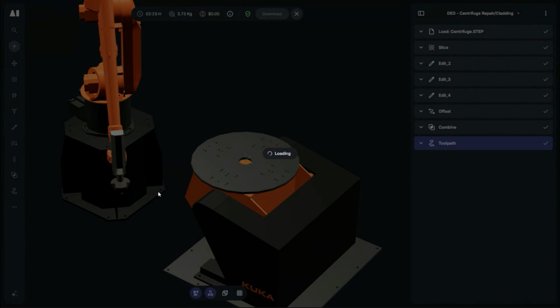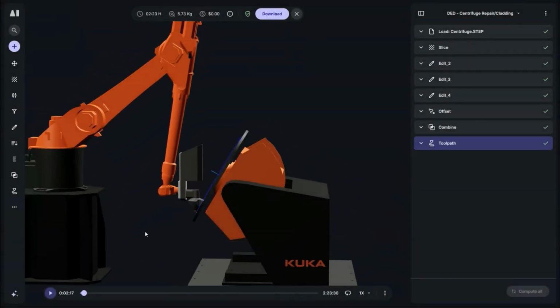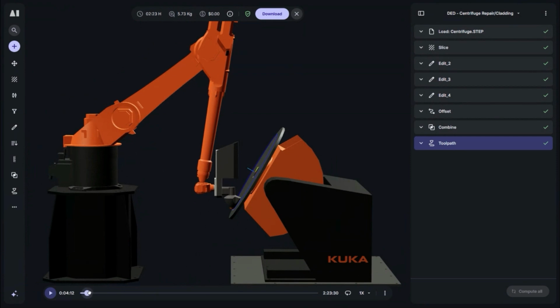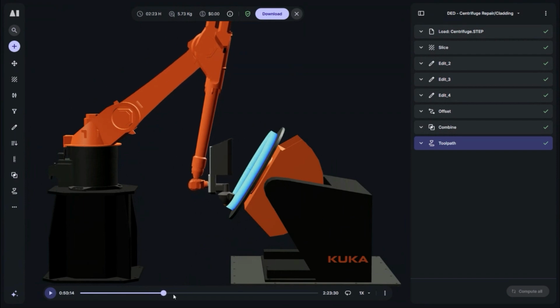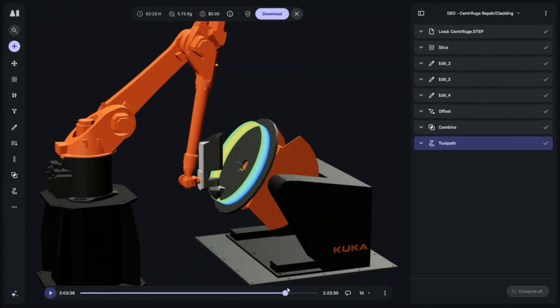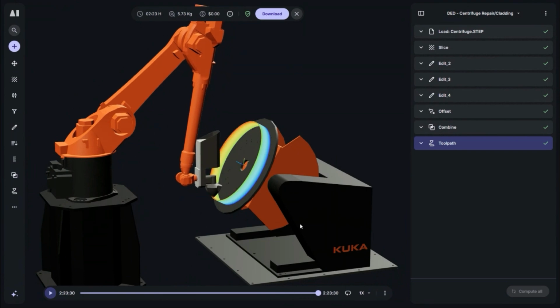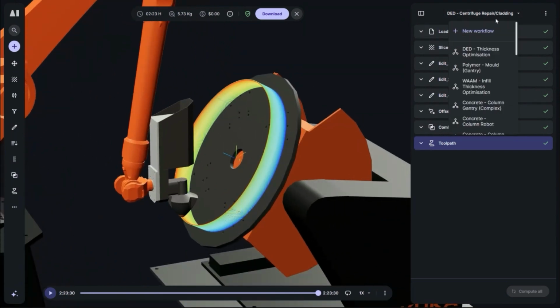And we can see what the effect of those tool rotations has been. So the bed will rotate, the tool is kept vertical, 60-degree deposit cleanly without colliding with the robot or the part, and we've applied our first wall, and then we can move in and apply our second wall of material. So we can very cleanly repair these kind of revolve geometries as well.